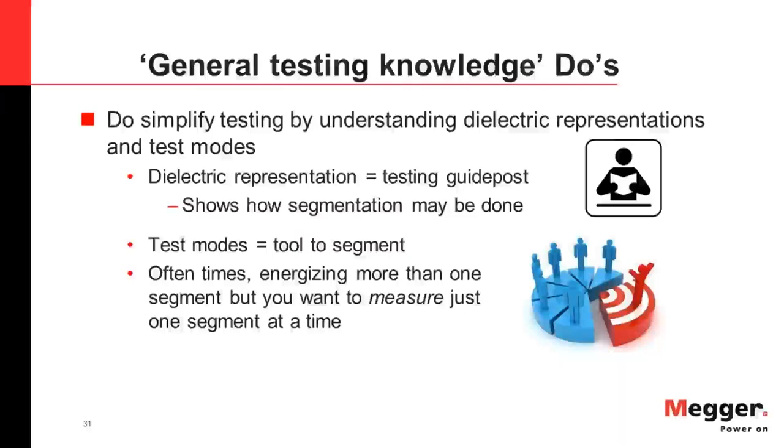Well, a dielectric representation is a testing guidepost that shows you how segmentation may be done. And test modes, meanwhile, are your tool with which to segment. Oftentimes, when you're doing a test, you are energizing more than one segment. Perhaps you're energizing the entire insulation system, but you really just want to measure one segment at a time, and it's the test modes that make that possible.